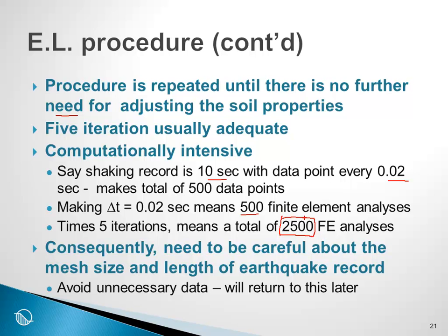So consequently, we need to be careful about the mesh size and the length of the earthquake record, because if we don't, we're producing a lot of unnecessary data, the analysis takes too much time, and the files get unnecessarily large and it becomes difficult to look at the results. We'll return to this a little bit later.